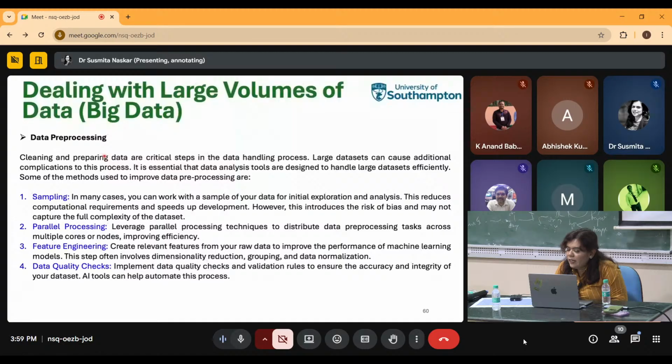And there are different ways we do that. I think all of you must have heard about sampling techniques. We also use sampling. Often you don't need to use the full data set. There are a lot of sampling techniques, like Latin hypercube or Sobol sampling. We don't need to use all 10,000 data points; among those 10,000, we may select 25 or 50 which we need for our case. That's called a sampling technique.